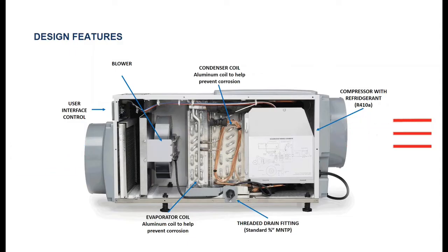The take-home message there is we do not want to adjust our Manual J calculations. The last thing you'd want to do would be to oversize an air conditioner because you're putting in a dehumidifier. That is going to create a cascade effect where that dehumidifier is going to have to run a lot because that air conditioner is going to short cycle.